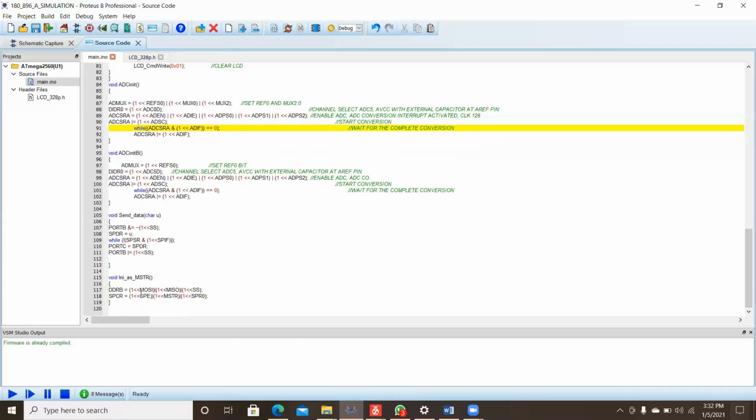And these are the functions for the master, in which data send is used to send or receive data. These functions are the same at port B. When we clear the bit of SS, SPDR is equal to 0, and through these conditions, port C will get the value of SPDR in port B, and at port B, SS is selected.